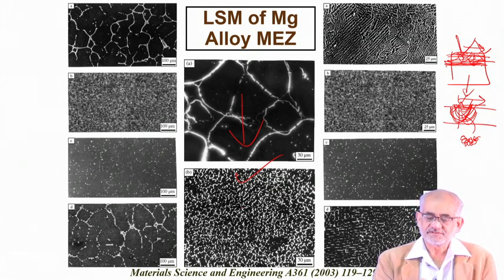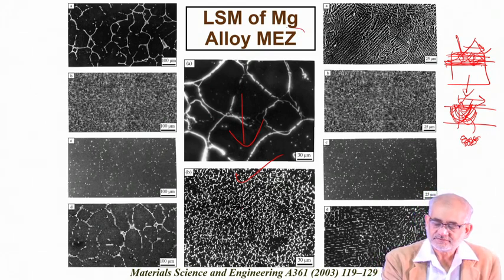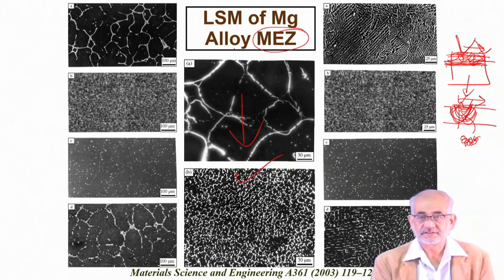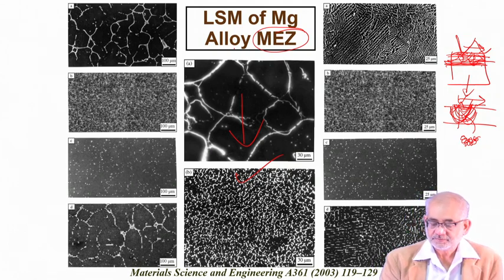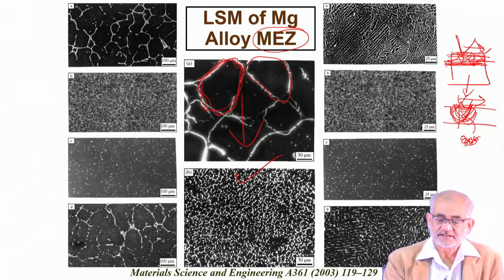And the advantage in this particular case, we are dealing with a rare earth added magnesium alloy. The presence of these rare earths allows formation of certain intermetallic aluminides or phases along the grain boundaries. As a result, these grain boundaries are decorated with compounds which are extremely resistant to chemical attack.